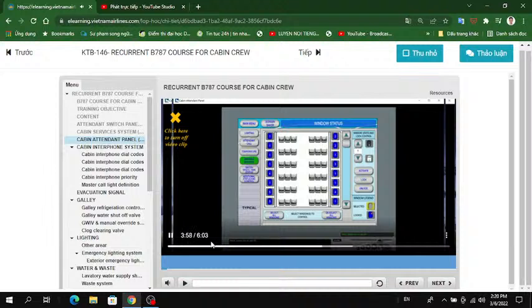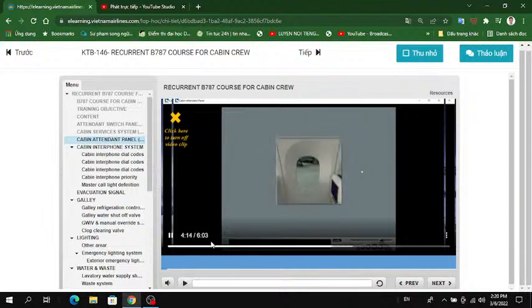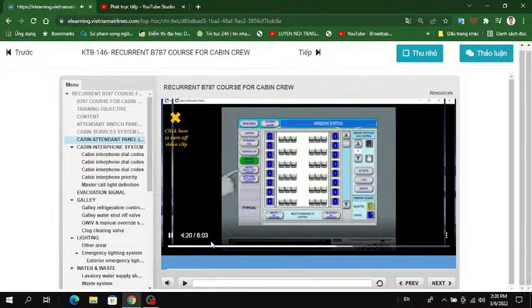Select Window icon at seat 9A. Set the window state to 2. Select Activate. The window has been set to a single darkened level of dimming. Touching Deselect All Windows deselects all windows in the cabin, including those not visible on the screen.